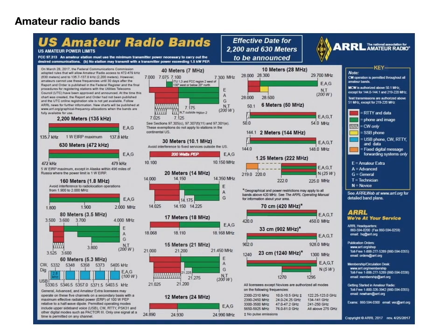Amateur radio operators can use many different bands of frequencies in the radio spectrum. Often these bands are referred to by their approximate wavelength. For example, the 80-meter band refers to frequencies between 3.5 megahertz and 4.0 megahertz. If you do the math, you'll find that a radio wave with a wavelength of 80 meters has a frequency of 3.75 megahertz, which is right in the middle of the band.